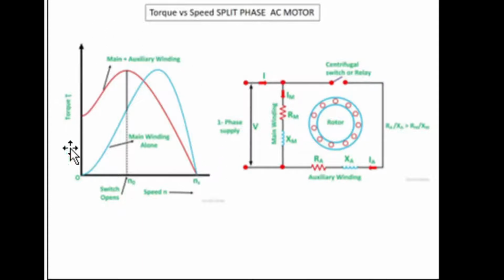So now if you go ahead and you plot the torque versus RPM of each of these coils as the current is being applied, you'll see that the torque maxes out on the start coil before that on the run coil. In other words, at some RPM less than the maximum speed of the motor, the torque on the start coil occurs. Sometime later, when the motor is running at its rated RPM, then the torque on the run coil reaches its maximum.